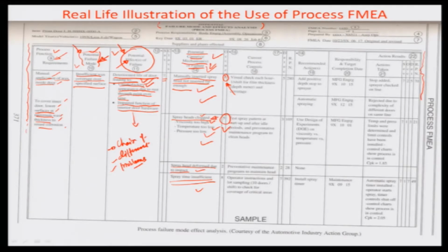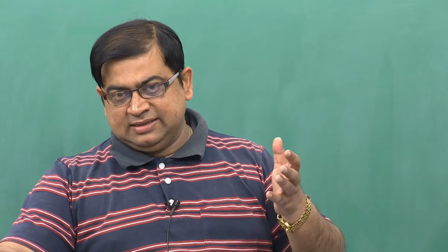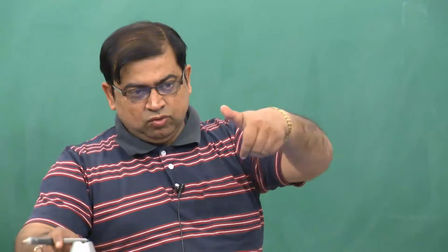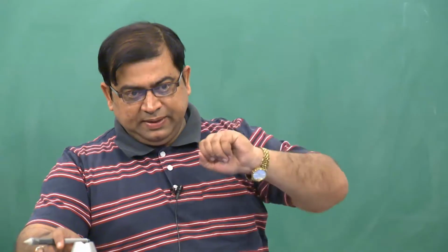obviously spray head deformed due to impact is quite less, maybe 2 out of 10 cases, or 20% of the cases. The operator may have accidentally rammed the nozzle against something to do some hammering action, which may have resulted. In this particular case, the hammering action may be just related to the door getting jammed, and you have to open the door in order to do this application.